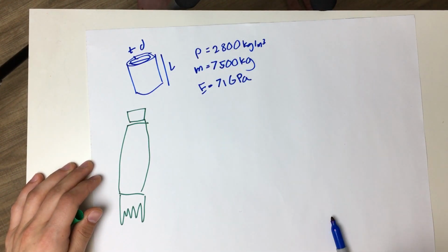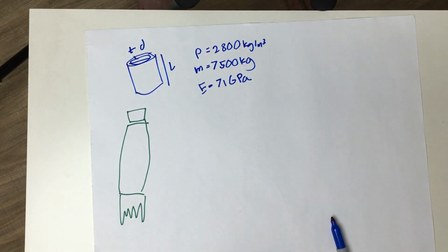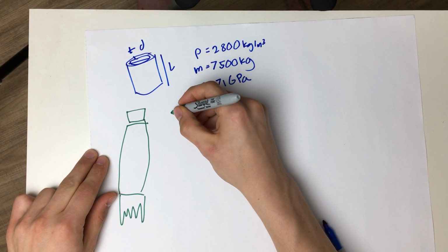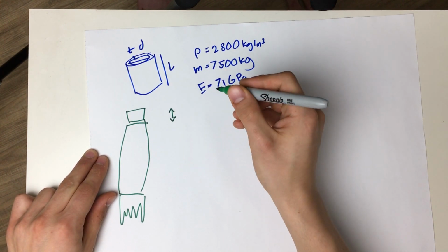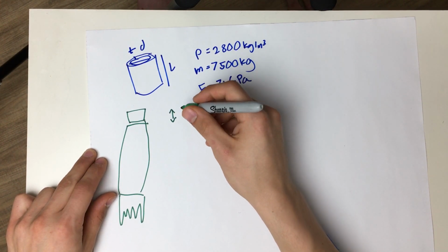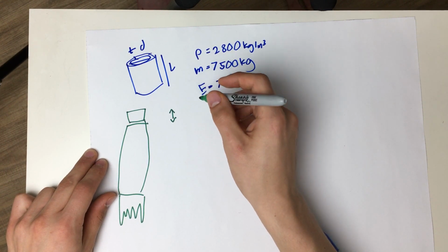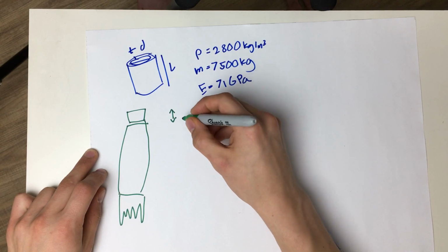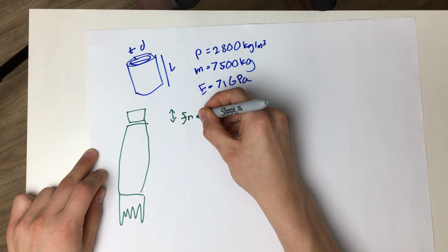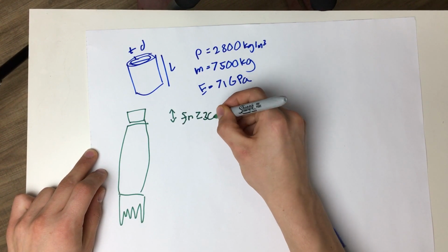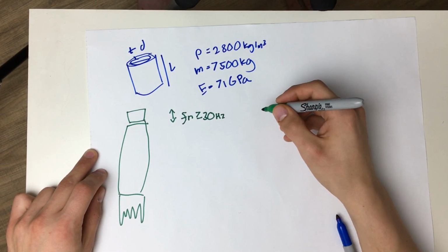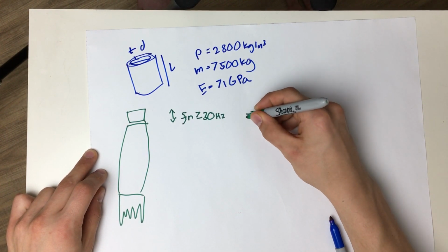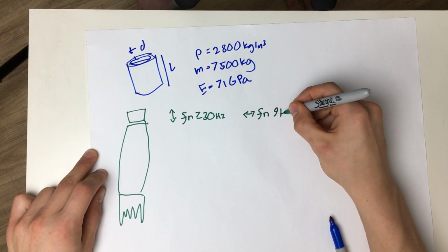and when the rocket ship goes up, there's going to be a whole bunch of vibrations, and we know that the vibrations are going to be in the lateral direction. The minimum natural frequency that the satellite can have is 30 hertz in the lateral direction, and in the longitudinal direction it can be 9 hertz.